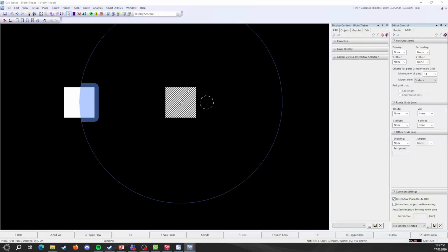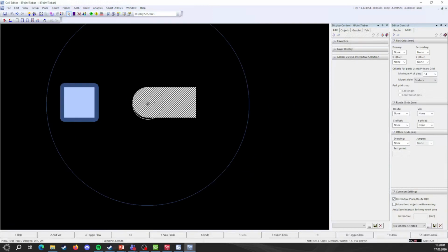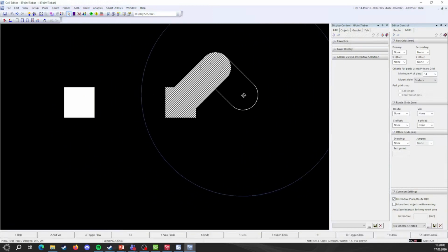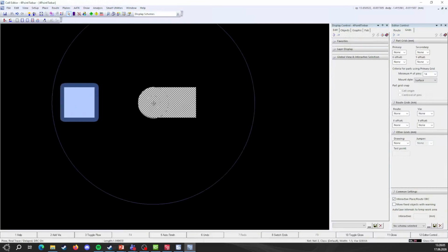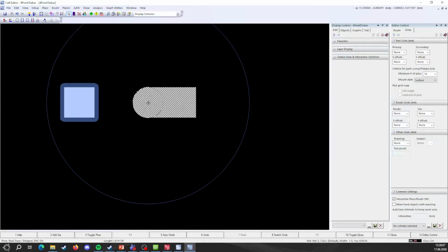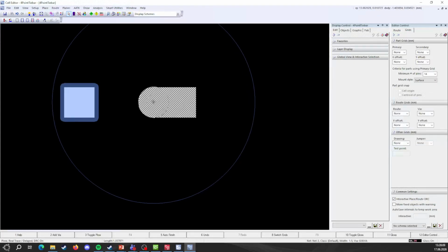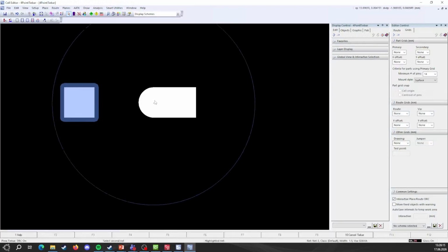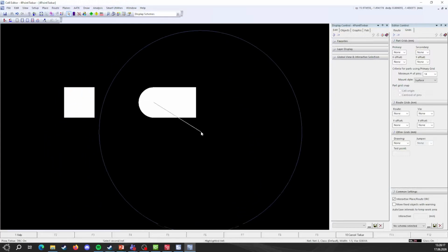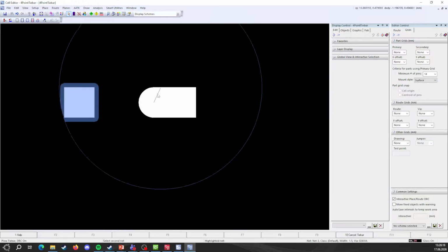So I will choose new custom width equal to 1.5 millimeter. I'm still in movement, so I didn't click anything. And while in movement, you need to press the T button, English T. After that, you get the red net connection.